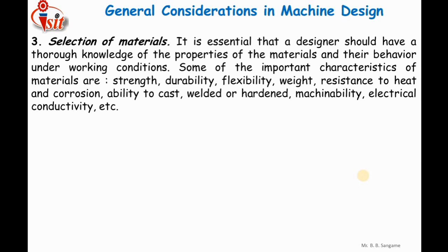It means that he should know what kind of material should be selected for the machine base, as the machine base might be subjected to various types of compressive loads and dynamic loads, and vibrations are induced. So a material like cast iron should be selected for the machine base, as it can sustain higher compressive load. Actually, cast iron has higher damping capacity, so that kind of knowledge is required.